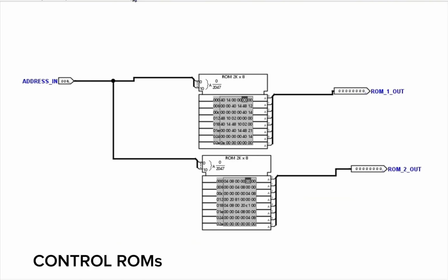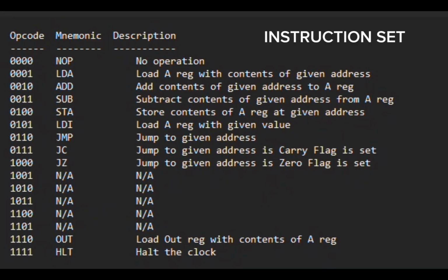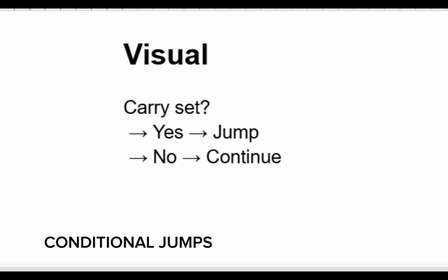The control signals are generated by two ROMs, namely ROM 1 and ROM 2. Their address inputs combine opcode, T state, and flag bits, producing the microcode outputs. By analyzing the ROM address space, the CPU supports these opcodes. Conditional jumps like JC and JZ depend on the flag register. If carry or zero is active, the jump control signal is enabled. Otherwise, the jump micro operation is skipped.